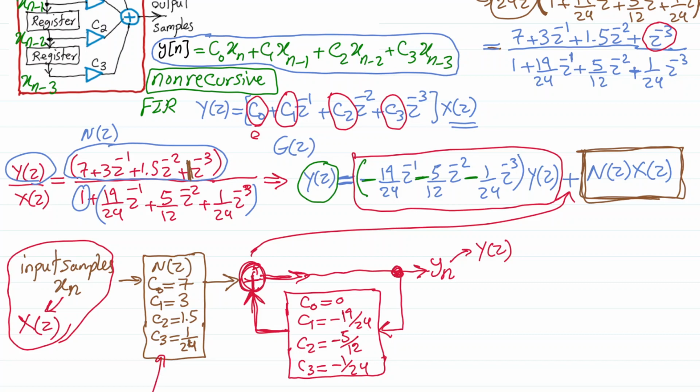Then we need to use an external adder that is interfacing between the two chips, because the second chip takes the final output samples as input, generates intermediate results, adds the intermediate results to the output of the first chip, and then the output of this adder will generate the final output that we desire.